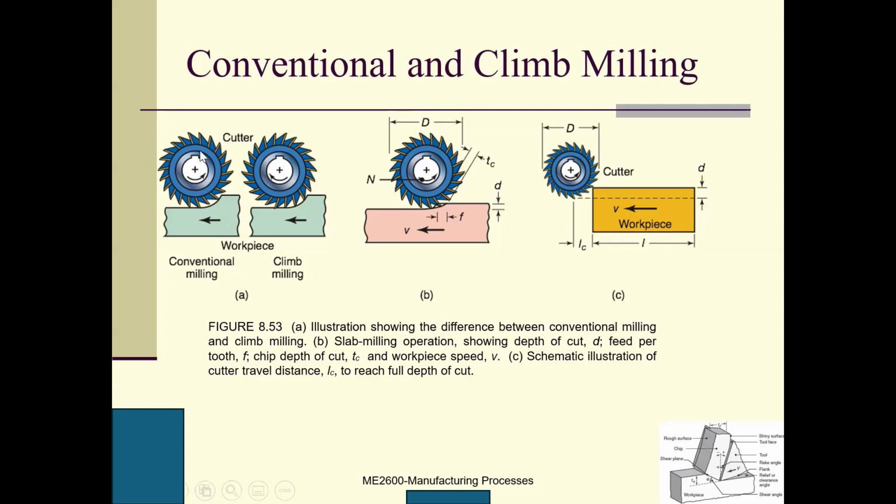So here, this is a milling cutter, and this is a workpiece. I'm sorry, the workpiece does not remain stationary. It is translating, but the milling tool is spinning. And in the lathe, in turning, the tool remains stationary. Here there must be a relative motion between the workpiece and the tool.